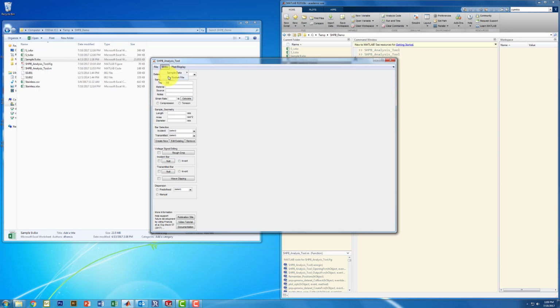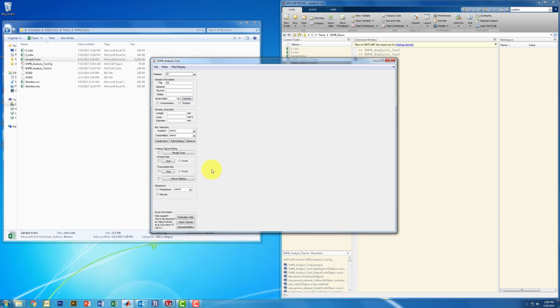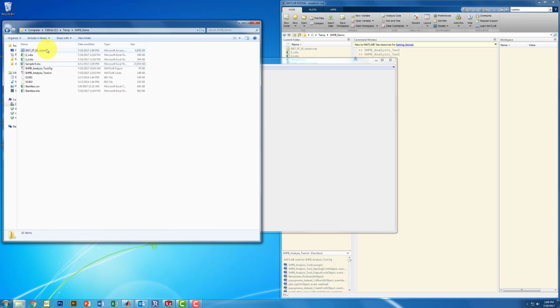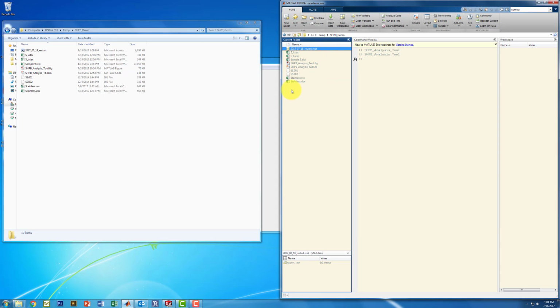We will go ahead and write a restart file from everything we've done from this point. We've got 4 different data sets loaded in. Let's go ahead and write a restart file. So write sample data, a restart file. You can name it whatever you want. The default's today's date and a restart. So let's save it in there. And there it is. If you're curious, you can see it here as well in MATLAB, and it's a structure that it's saving.